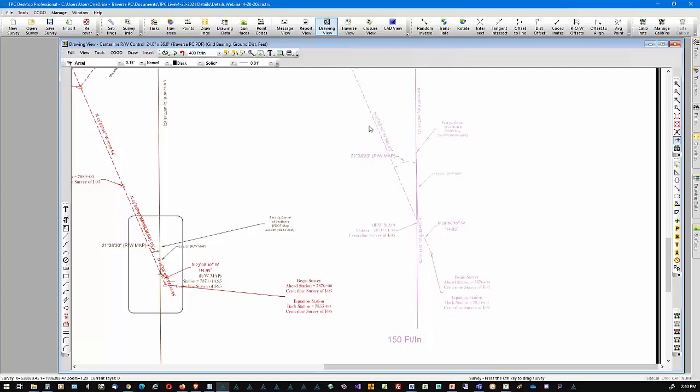All right. If I want to draw something and add it to this group without going into edit mode on the group or without exploding the group, then it has to be snapped to one of the objects in here. All right. So I've already got an interior angle here. Actually, I'm going to show that to you in the next file that I'm going to load up. So I'll show you that part. So just be aware that I can add things to the group if I have attached them to one of the group objects.